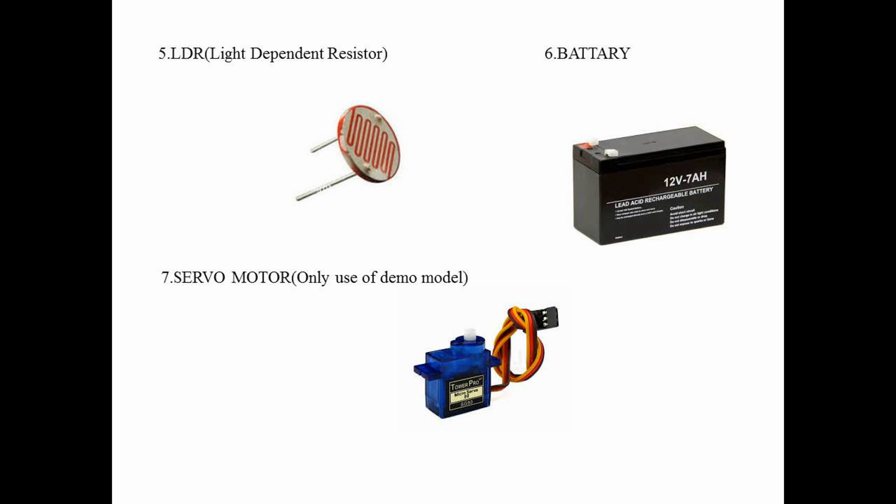These resistors are used as a light sensor, and the applications of LDR mainly include alarm clocks, street lights and light sensing meters. The specification of LDR: type coating, light resistance 10K to 20K, dark resistance 2M, impressed voltage DC 150 volt, operating temperature -20 to +60 degrees Celsius, power dissipation at 25 degrees Celsius 30 mW.